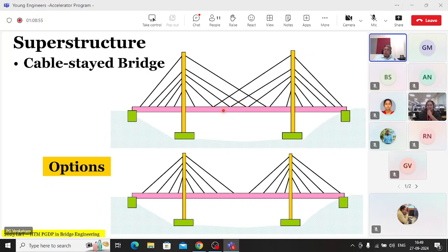As you pointed out, the crossing arrangement is not easy. These cables tend to clash with each other. You have to adjust the geometry tightly, and when you tension it, they tend to cut against each other. All that creates a problem. So we don't do too many. We go to this example. Structurally, this is better. Construction wise, this is better. And so most cable stayed bridges have veered towards the second option.